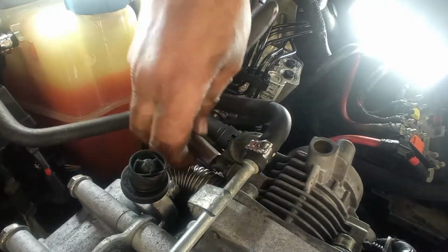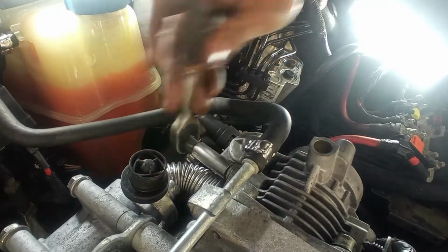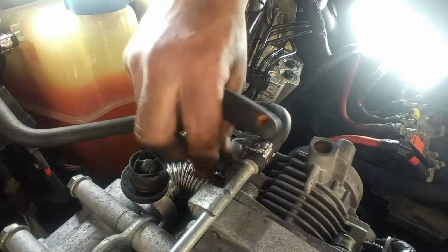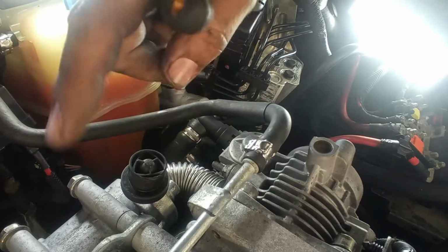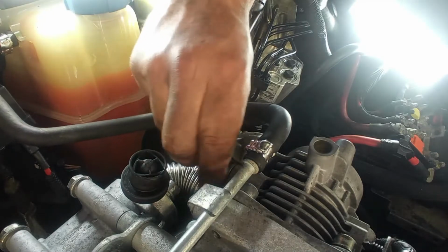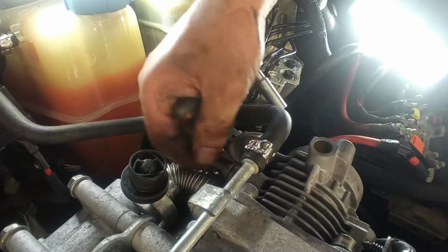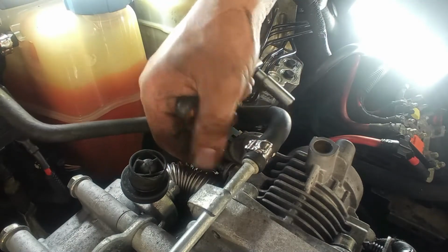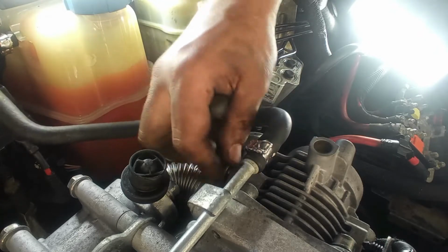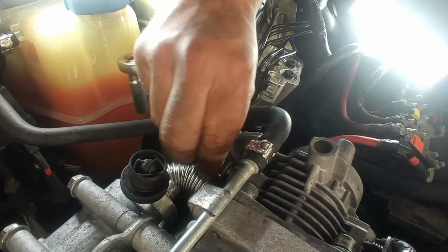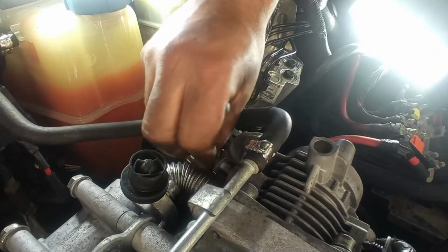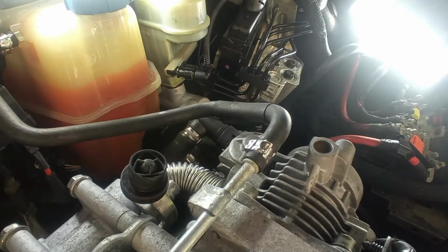I also have to mention that this car had a very large fuel leak. Turns out the high pressure pipes that go to the injectors were loose. I was expecting a correct rail, but in fact I tried to tighten just to check the tightening of the pipes. They were all loose. Yeah, that also may affect some things.